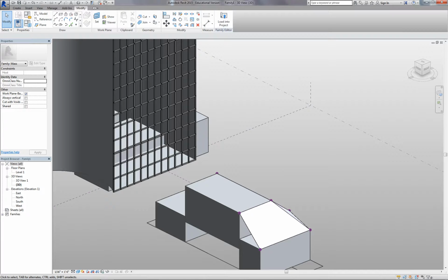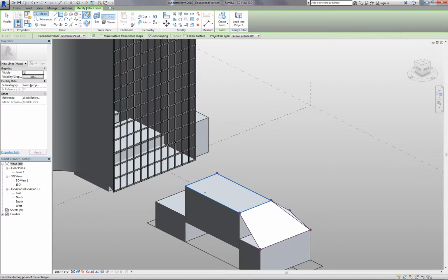And then we can get into what becomes an opening. We can't just take things into surfaces, but we can start to punch openings through this, like we do the voids. So if I come here, I can set an offset.